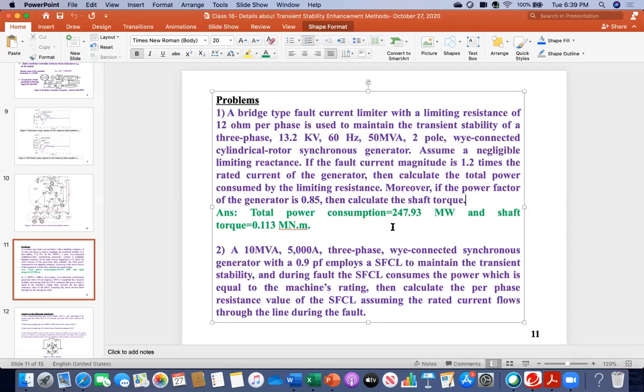I think the power value should be 42.50 megawatt. Amani, what power factor did you use? 0.85. I got 58.82. It's supposed to be 0.85 multiplied by 50, so it should not be 58. You are multiplying by 0.85, so it must be lower than 50.